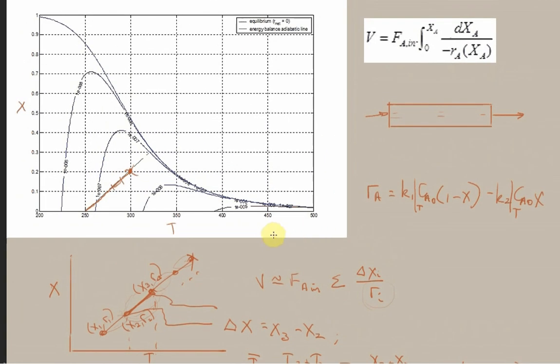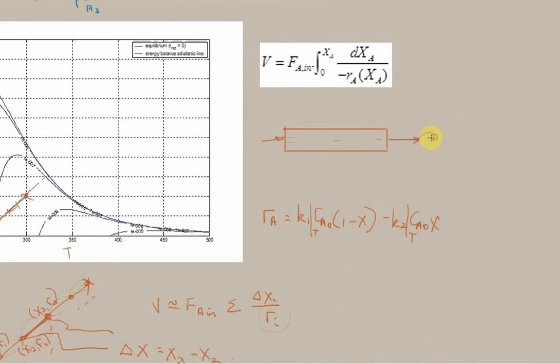Right, so that's the PFR, and of course the usual applies that we could have interstage cooling, so we can do interstage cooling for the plug flow reactor as well, and we can have more plug flow reactors like that. So all those proofs and so on about using the overall conversion still apply here.